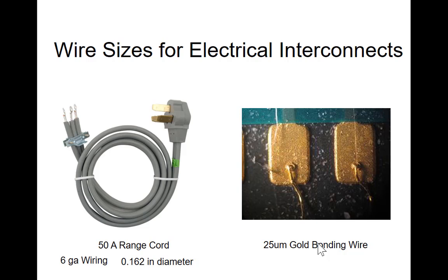Yes? Concerned about breaks, fragility. Yeah. If you look at a wire that's 25 microns in diameter, it doesn't have much strength to it. And if you try to make that smaller, we don't have good ways to physically move those wires around. So that's a good observation. The mechanical strength of gold has not changed in 30 years, and it won't change in the next 10 years.